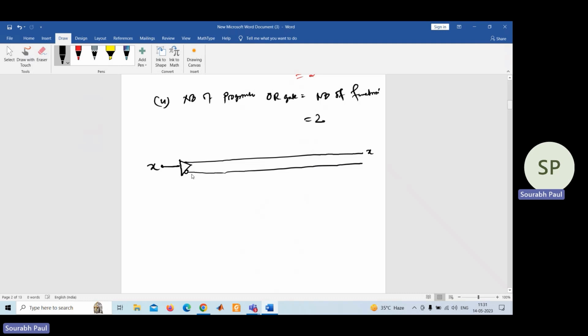This line will give you exactly X and this bubble line will give you X bar. And this is the input buffer. Now you need to do the same thing for variable Y, because you need to use 3 input buffers according to the question. So here also you will get 2 things: one is Y, another one is Y bar. And you need to do the same thing for variable Z also.